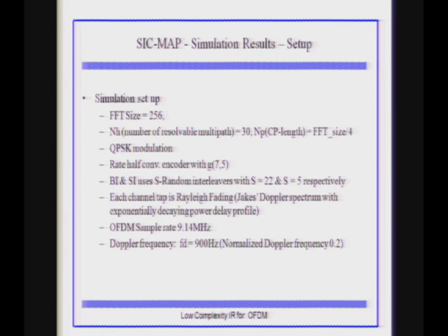We are just making a brief mention at the end. That is one of the challenges for 802.11, for example. You have to come up with a modified scheme. There is a certain specification in the standards as to how much delay it can tolerate, and if you introduce such interleavers, it cannot tolerate that. Then we have to come up with slightly different schemes.